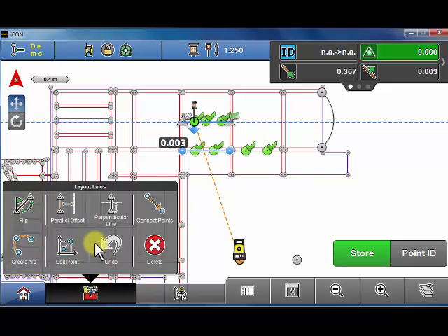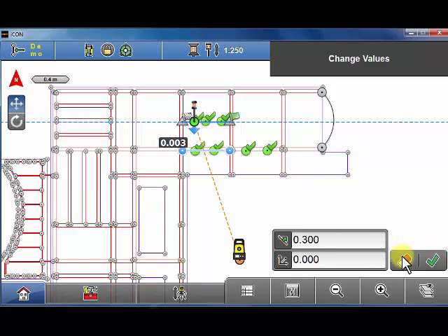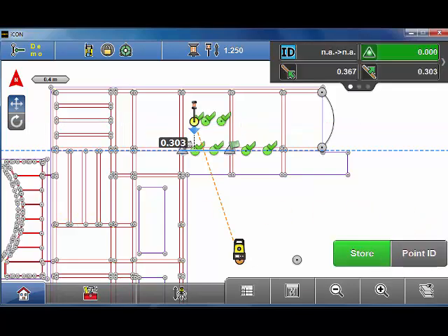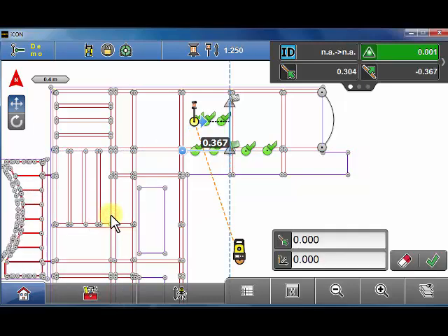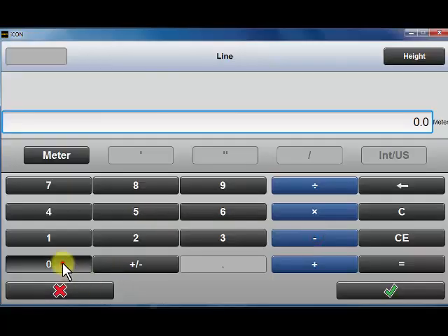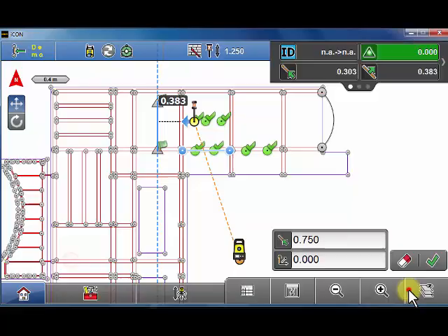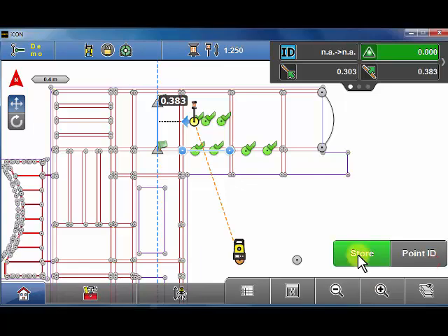The grid can be intensified either by applying a parallel offset or by creating perpendiculars to the construction lines. The Perpendicular Line tool offers the possibility to create a perpendicular line to be set out. Let us imagine we have to lay out a line perpendicular to our construction line. We can choose the position of the new perpendicular line in relation to our reference line.